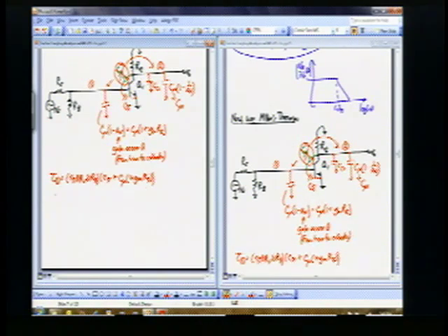Okay, and now I can do the same thing for node 2. At node 2, I just get all of that resistance in shunt with that node, which is just RC, really R naught parallel with RC. And then times all the capacitance in shunt with that node, which is now C mu plus C sub S. And then finally, from both of these things, omega H is just 1 over the sum of these two time constants.